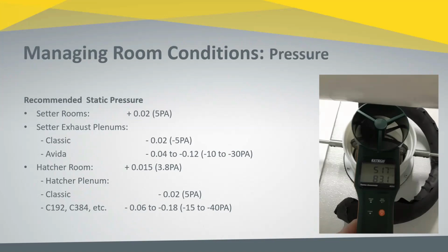But then as you progress through hatch, the chicks pip, they get into a dry down mode. Now you have down that you have to deal with collecting on the cooling coils. At that point, it's very common to take a plenum slightly more negative and aid the machine with additional airflow, and therefore you get closer to that 12 to 15 CFM per 1,000 eggs in order to manage vent temps leading up to pull. So this is kind of related to that last comment you made.